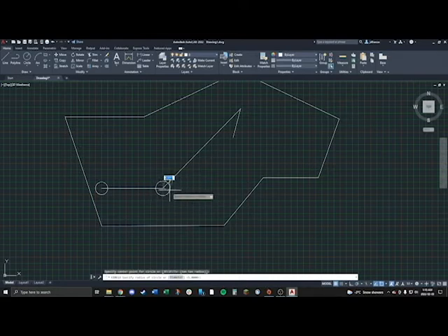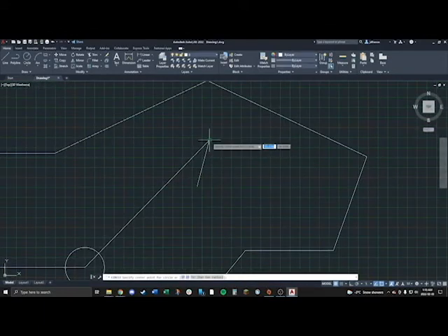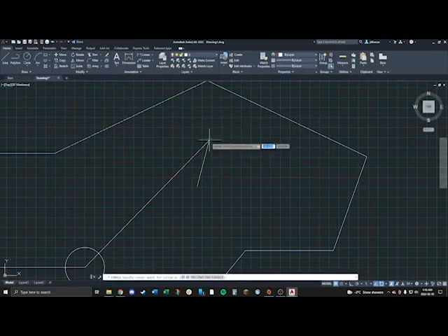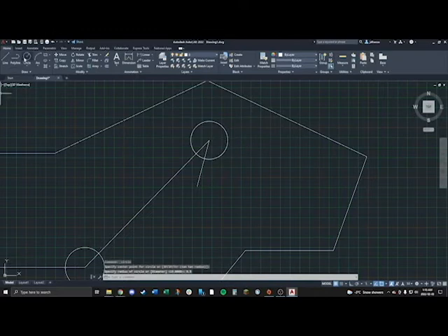And here we're going to make this one 10. And then we get up to the fun part here. This is what confuses a lot of people. So we know that these both need to be 19. So this is going to look a little funky because I'm actually going to change that because that was wrong. I inputted a radius of 19. However, if you notice, there's a diameter of 19, which means the actual radius is 9.5.